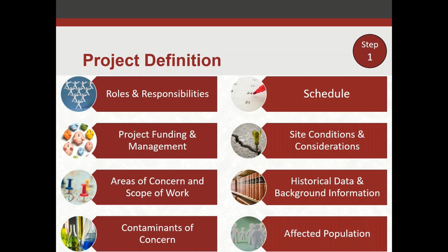Site conditions and considerations. You're not going to know everything up front, but if there are obvious things that are going to create an obstacle in doing a survey assessment, for instance, site access is going to be a challenge, or there's site operations that need to continue that you're going to have to work around. So knowing those up front, so you can scope a hazardous materials assessment and design, it's important to have that information provided.